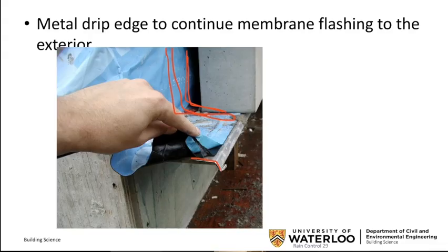And it will expand and contract with temperature quite a bit in Canadian buildings. And therefore, whenever you lap two pieces of metal together, they're going to move back and forth and make it difficult to seal them in a watertight manner. However, by using the membranes that are flexible and sticky to themselves, you can solve those problems of movement.